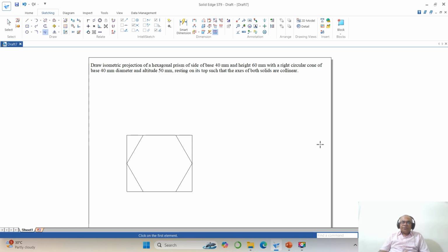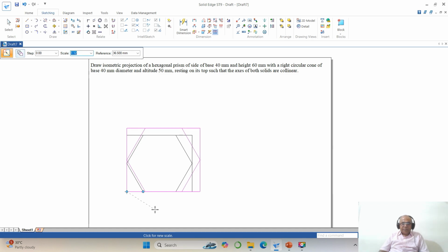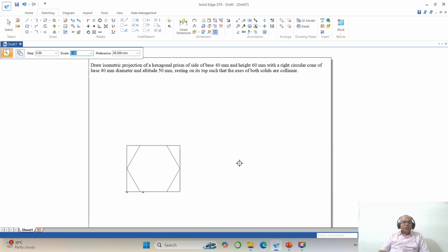Now I want to reduce it to isometric scale. So to do that, I will go for a scale. You select this, take endpoint, make it 0.816. So this is the reduction in scale. Now once you do that, we have the reduced scale. So the first thing I need to do is iso scale used. So you take 3 mm, okay, take it, then say iso scale used.